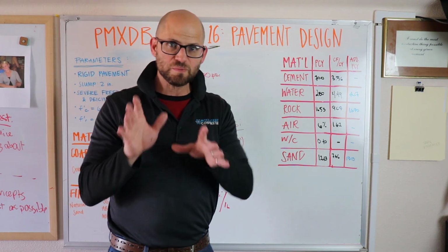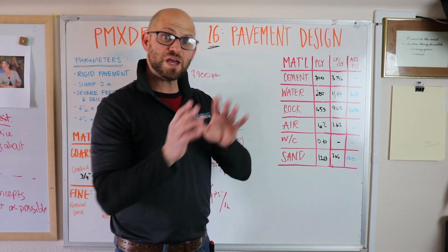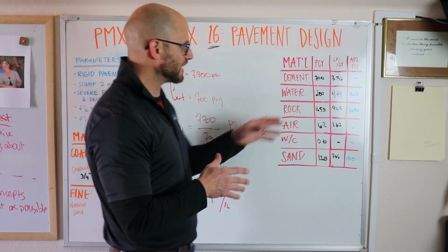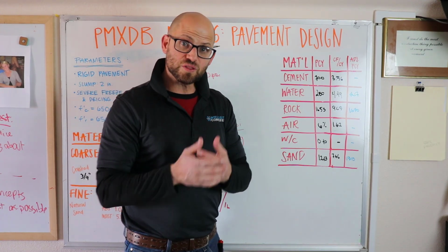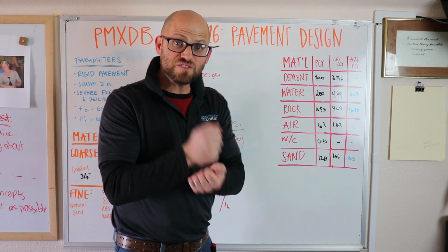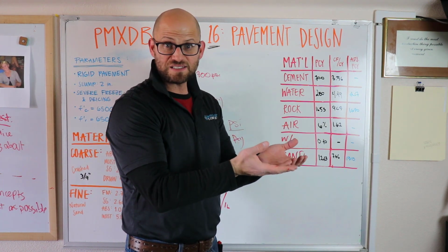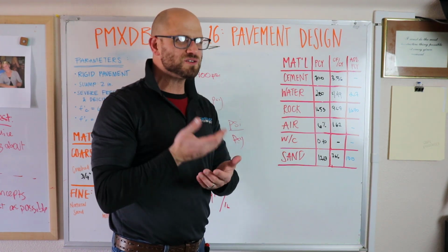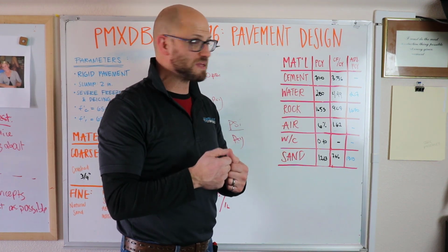We want to use, God bless cement, especially Portland cement, where it has gotten us in the last however many years is absolutely amazing compared to where we started with natural cements and these other materials out there. But with cement, we want to be careful because we can also induce cracking. There are some things that we don't want out of it. So we want to use just as much as we have to. And if we can increase the efficiency and pull some of that powder back, as Haley said, not only to save the environment and increase the durability of concrete, that's never a bad thing. And we're also going to see a value-added performance or a reduction in cost. As Haley said, that's one of our most expensive things in the concrete.